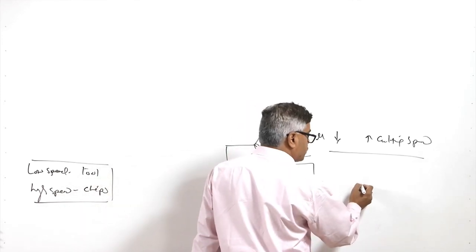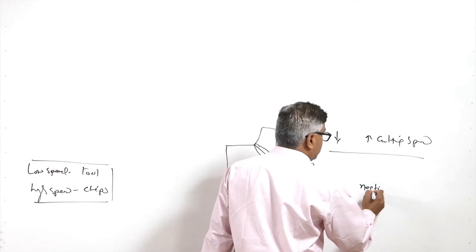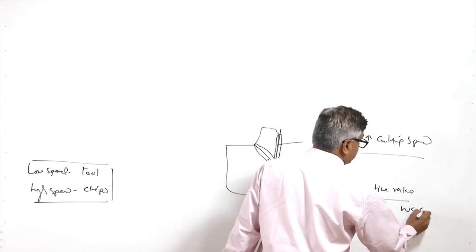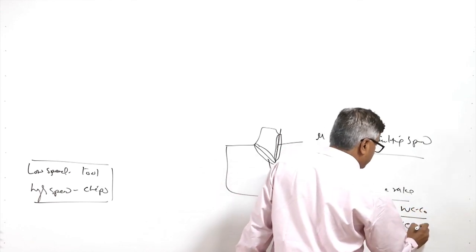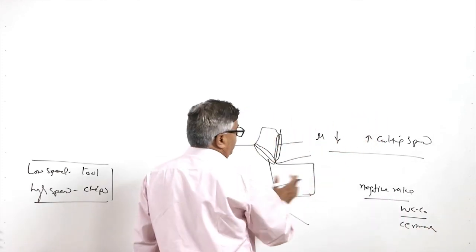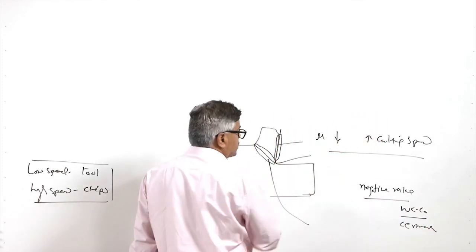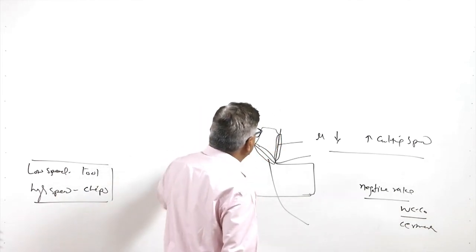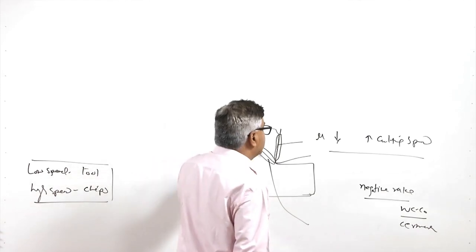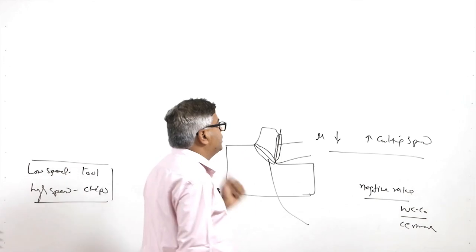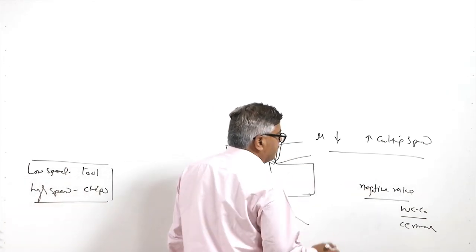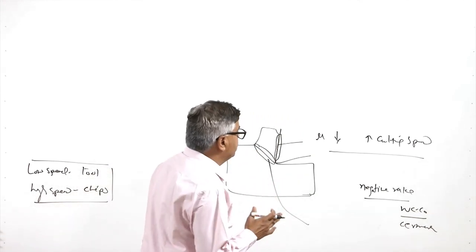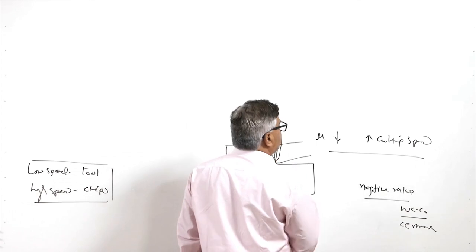But in those cases where the negative rake tool is used, like in tungsten carbide, cobalt, or the ceramic tool, at high speed heat generation leads to the softening. So, increase in speed leads to the softening of the material at the cutting edge, and that in turn reduces the energy required for the shearing. But at low speed it does not happen, and even with the positive rake it does not happen, means speed does not affect things much with the positive rake angle tools.